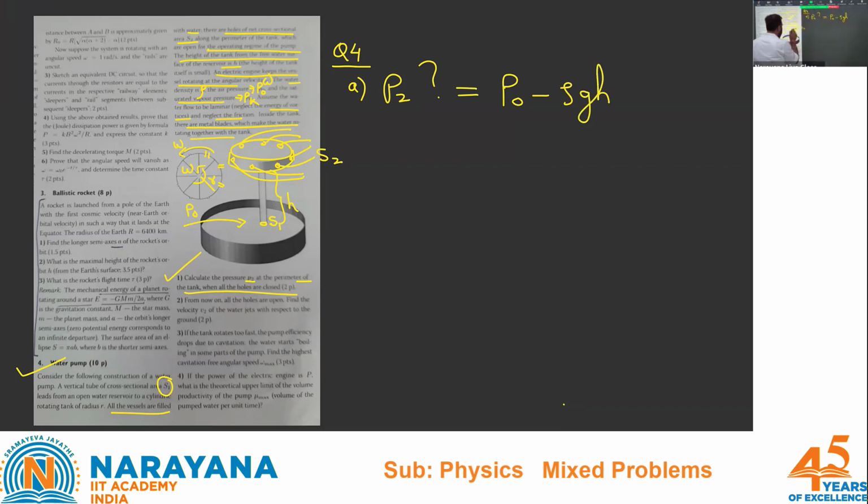So now I have reached the center of the upper disk, and now from the center, because of omega, there is centrifugal thrust which will change the pressure parabolically as you move radially outwards, and that term will come out as rho omega square r square by 2. Check this. Even if I take a cylinder and just rotate it, that pressure can be written easily. Or directly also you can write by center of mass. Yeah, that's fine. So A part was simple, right?